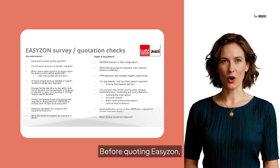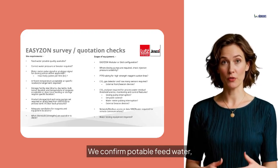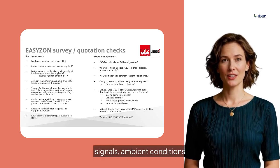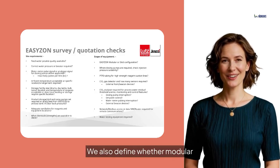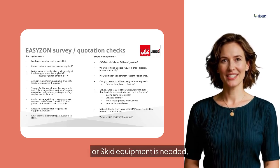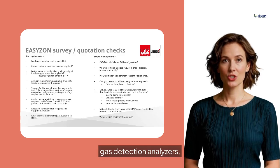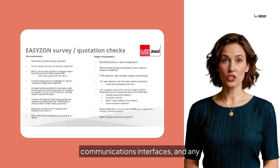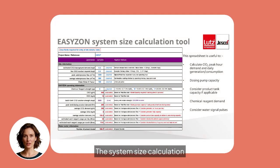Before quoting EASYZON, a structured survey is required. We confirm potable feed water, pressure and metering signals, ambient conditions, and storage facilities. We also define whether modular or skid equipment is needed, dosing pump requirements, gas detection, analyzers, communications interfaces, and any water testing equipment.